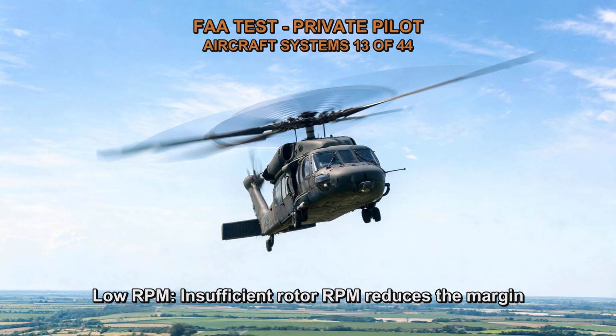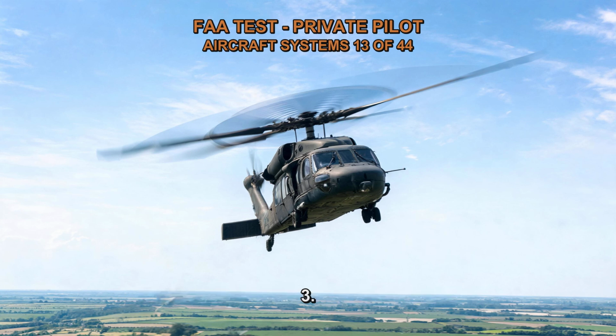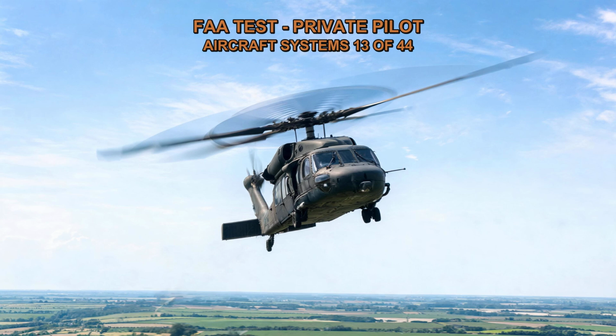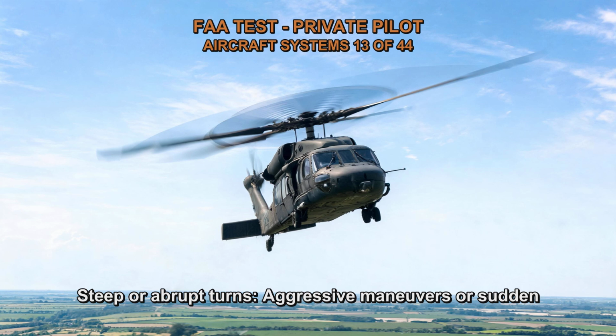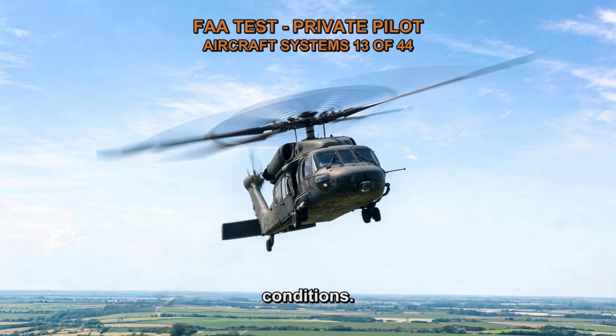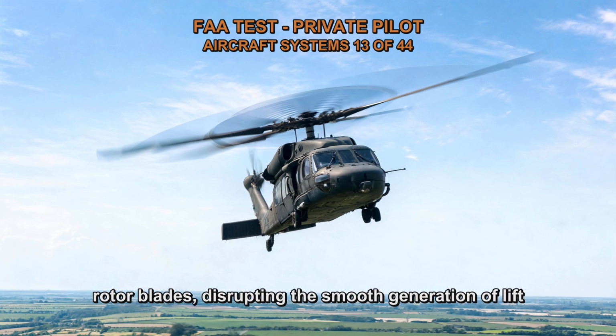2. Low RPM. Insufficient rotor RPM reduces the margin of safety and increases the risk of retreating blade stall, particularly at high airspeeds. 3. High-density altitude. Operating in high-density altitude conditions, where the air is less dense, reduces the rotor's ability to generate lift, making stall conditions more likely. 4. Steep or abrupt turns. Aggressive maneuvers or sudden changes in direction can increase the angle of attack on the retreating blade, leading to stall conditions. 5. Turbulent flight. Turbulence causes irregular airflow over the rotor blades, disrupting the smooth generation of lift and increasing the chances of stall.